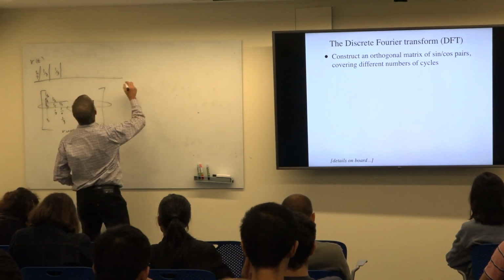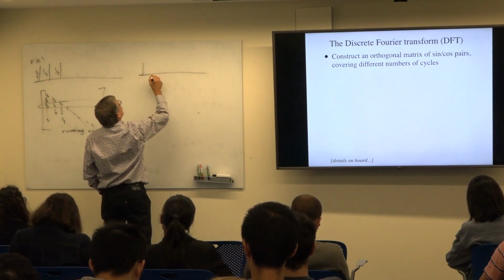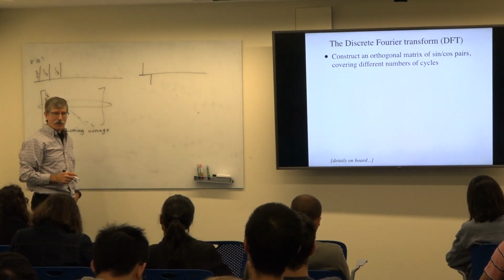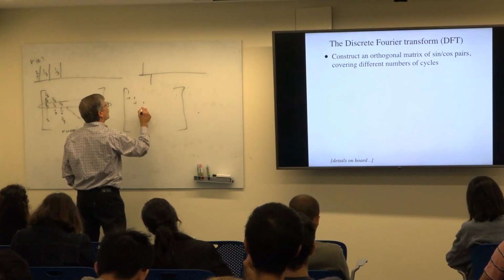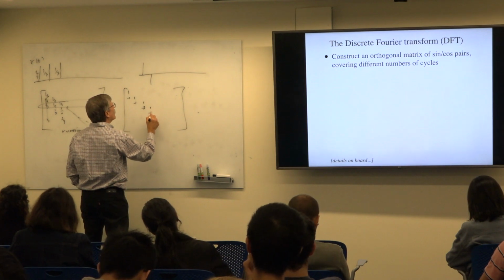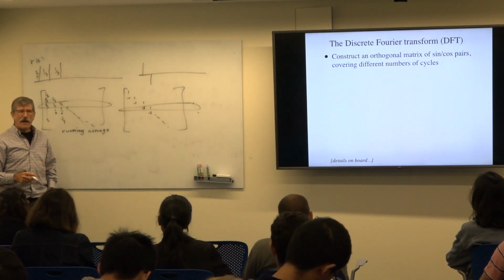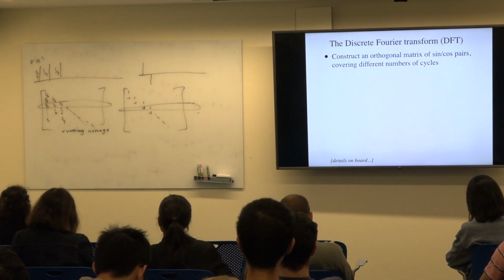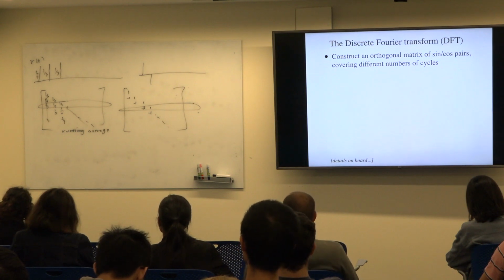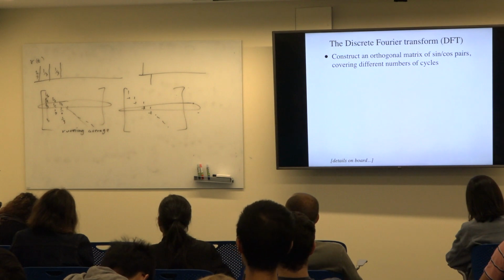Let's try another example. Let's suppose that the impulse response is 1, minus 1. Okay? So here's our matrix. 1 minus 1, 1 minus 1, 1 minus 1, and so on. Let's take any given row. This is the 4th row. The output at time 4 is the input at time 4 minus the input at time 3. So it's computing a difference. It's computing the discrete time best you could possibly do, which isn't very good, of a derivative. It's saying, what's the slope? How much are things changing right now?